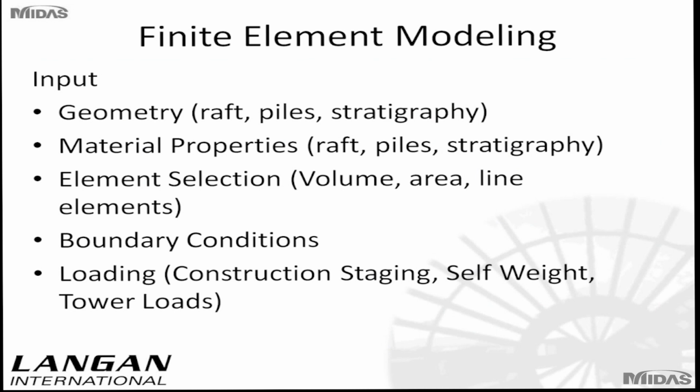Typical input using the finite element method consists of defining the geometry, the raft, the piles, the stratigraphy, the material properties, the element selection, if you would use volume elements, area elements like plates, or line elements like beams, the boundary conditions, and the loading, which typically you could consider a boundary condition. And with the loading, we mean the self-weight of the soil, the tower loads, and you would consider also construction staging during the construction of the foundation, maybe to model an excavation.